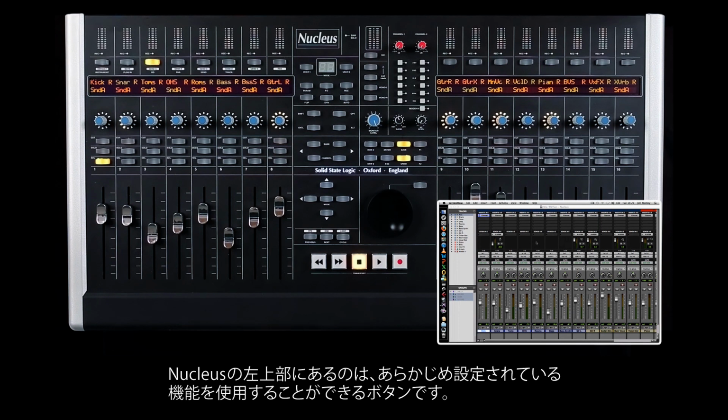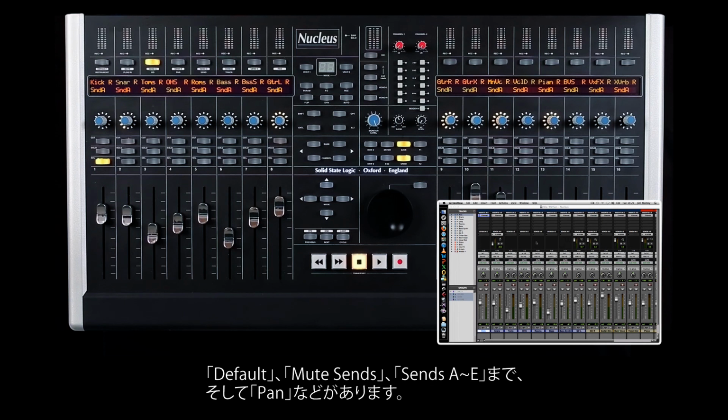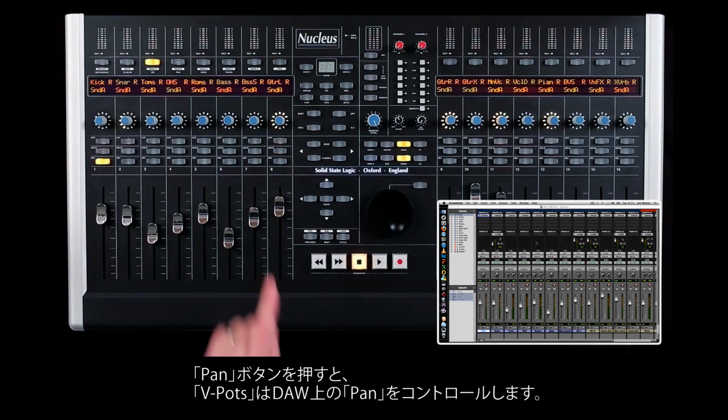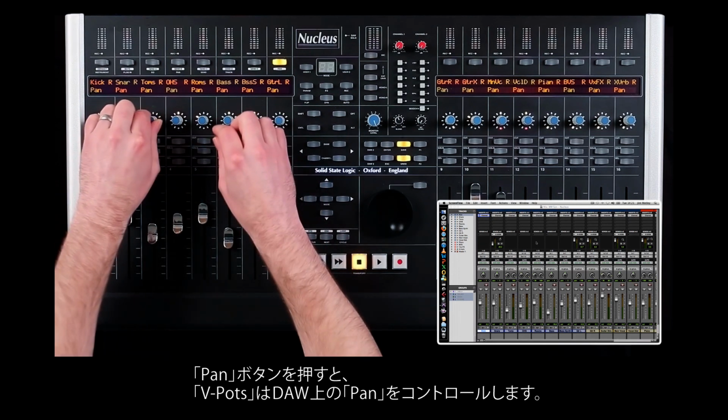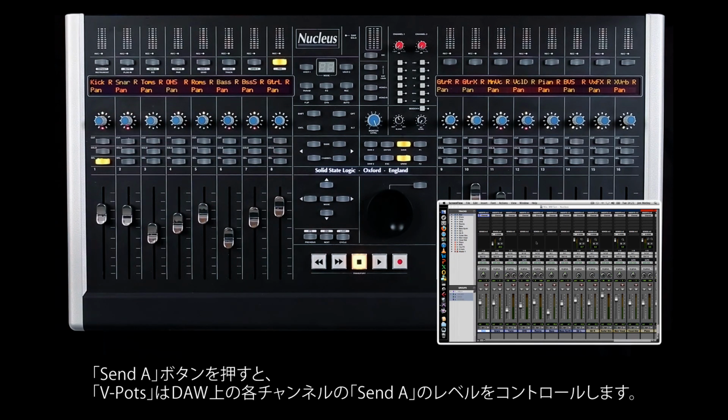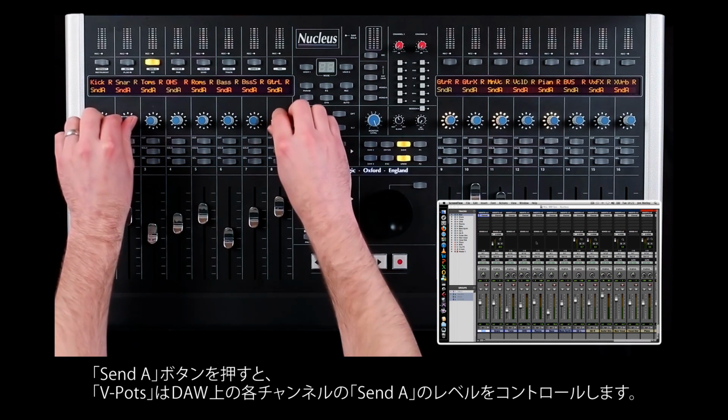You will notice the top left-hand buttons on Nucleus are pre-labelled with a selection of the most useful functions, including default, mute, sends A through to E, and pan. Pressing the pan button will set the rotary V-pots to control pan. Selecting the Send A button, the V-pots will now control each channel's Send A level.